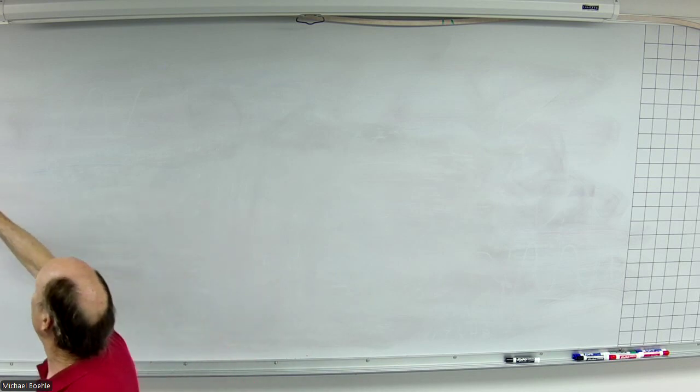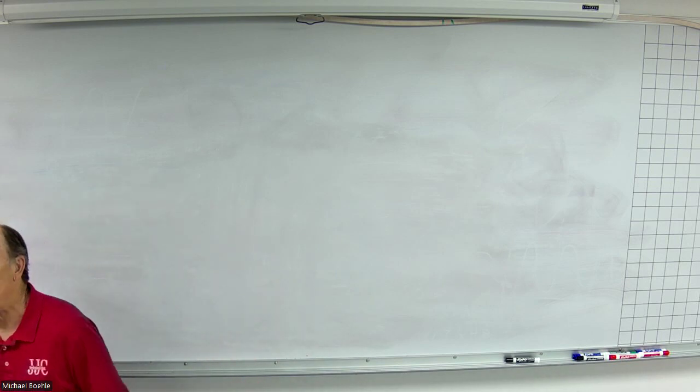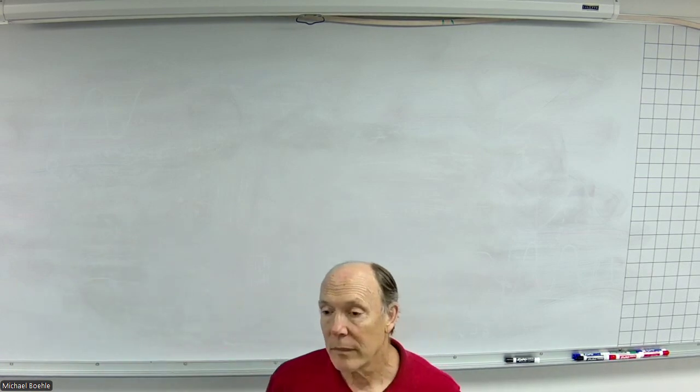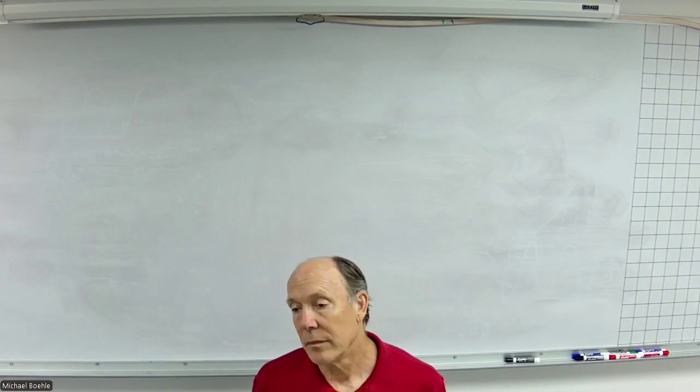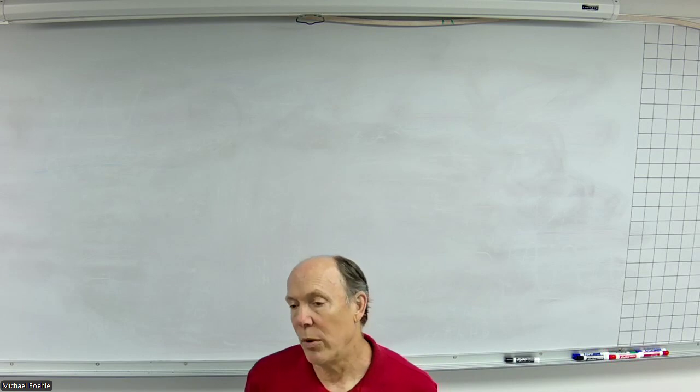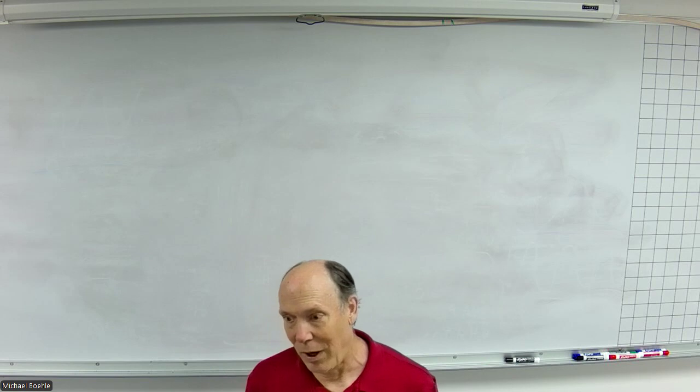But now, it's a little bit different because of using this part here with the feedback. You want a very high Q, you want a low denominator. So you have to try to set your A sub V to be very close to 2. Which would require precision resistors probably to make sure you don't go beyond that.